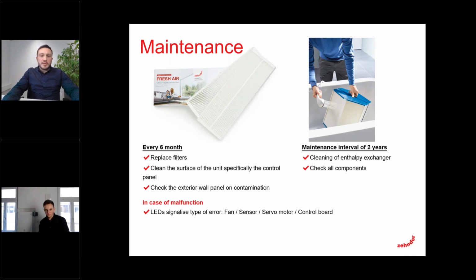And with the filters, well, we have a filter indication LED that actually tells you when a filter should be changed, but we recommend changing the filter every 6 months to guarantee that you have clean air, that you have hygienic air, and that your decentralized unit is also working very well.